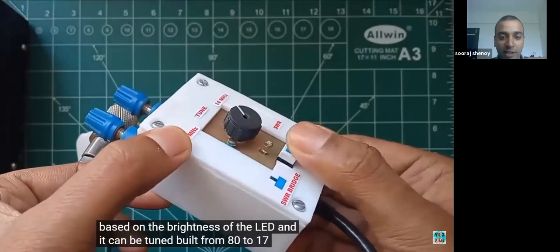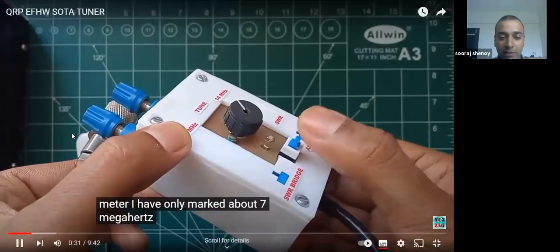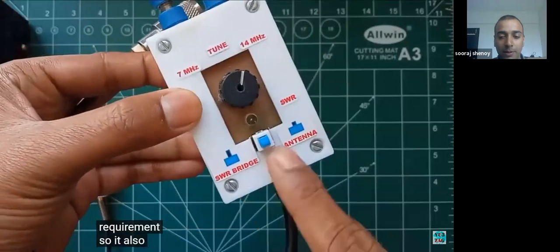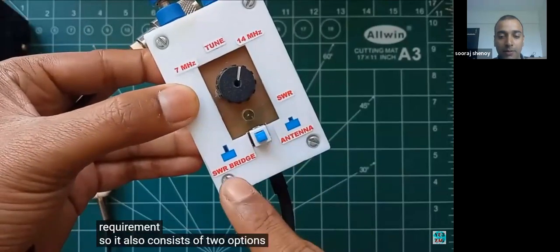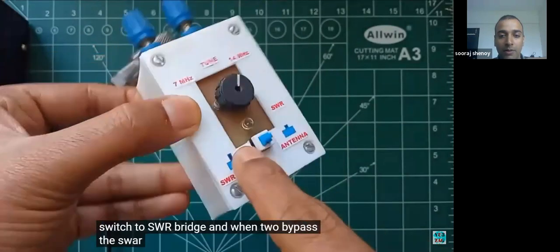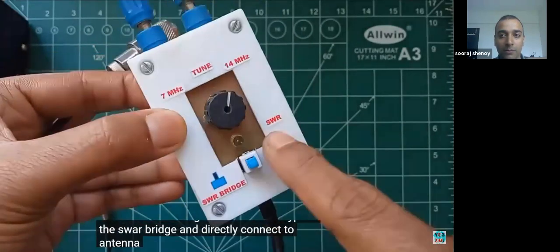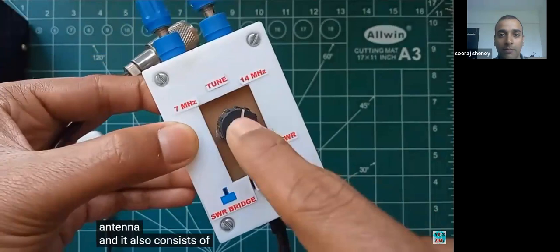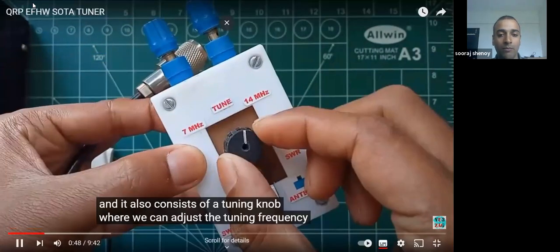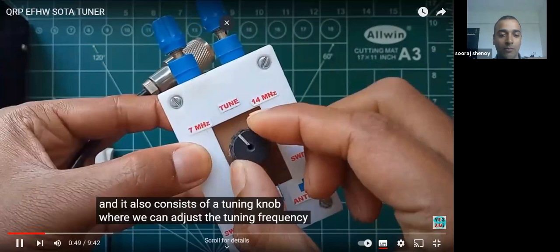I have only marked for 7 MHz and 14 MHz as per the requirement. It also has two options: one to switch to the SWR bridge and one to bypass the SWR bridge and directly connect to the antenna. And it also has a tuning knob where we can adjust the tuning frequency from 7 MHz to 14 MHz.